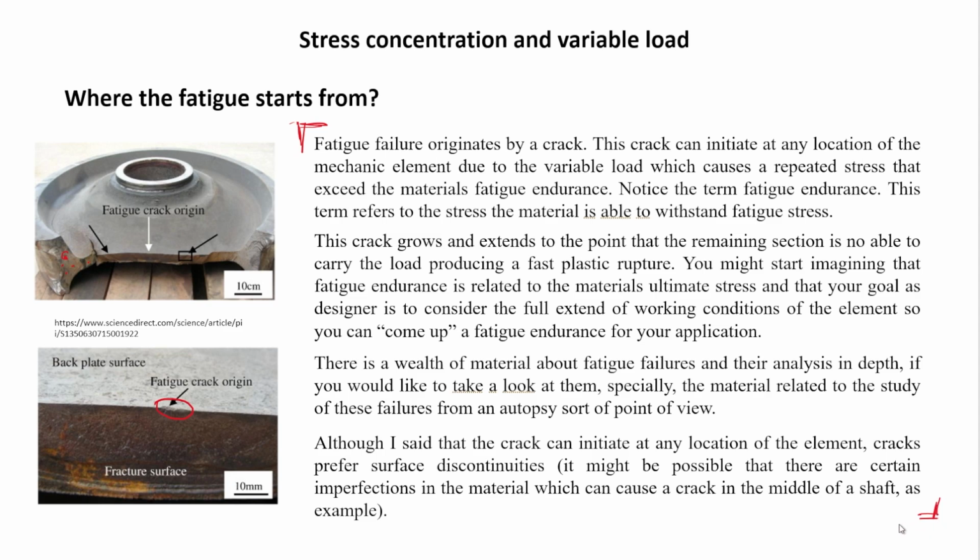But we can stick to this definition of where fatigue starts and how the whole process goes, and it's pretty simple. As an engineer, let's try to keep things simple. Somebody asks you how fatigue starts. Well, because there's an imperfection. That imperfection generates a micro crack, and from that micro crack it starts growing until the remaining section trying to withstand the forces is so small that it breaks suddenly.